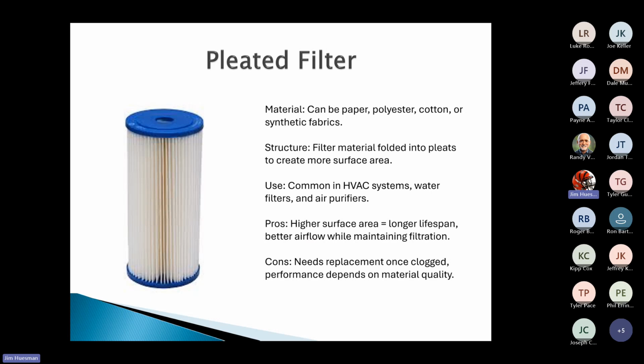Also, one of the big ones, most pleated filters, I know if we get into a brand that I represent, their filters are able to be cleaned. I normally say 1 time. And the reason I don't say 2 or 3 is as you're in there squirting each one of those areas out, you're weakening whatever that material is. So I would say, hey, with any pleated filter, you can reclean it. You can clean it. But I'd say just about one time and then toss it.